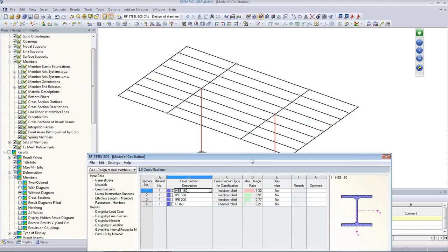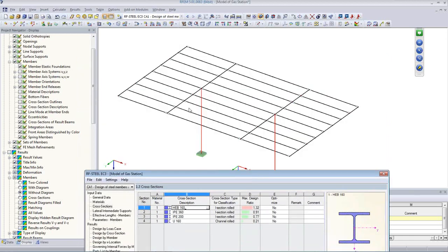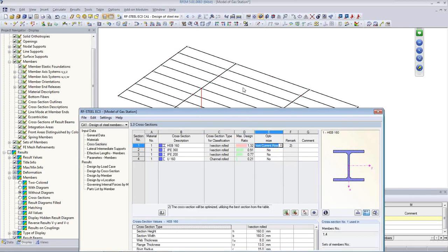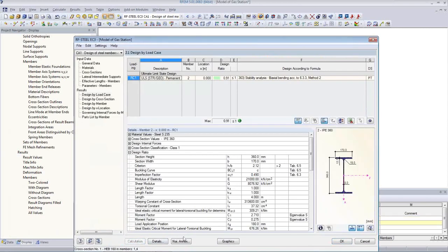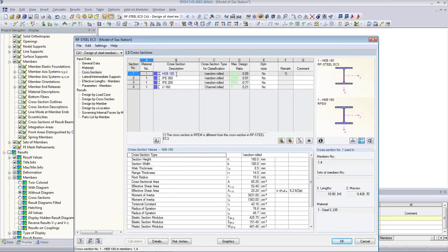I have not taken care of the serviceability and the deflections. So therefore, and I know in these cases we have a problem with deflections, because the columns, if they are weak, the whole roof will kind of wiggle back and forth. So I have to optimize one more time this cross section, and most likely I have to even choose a higher one. Also controlling is the serviceability, and for this probably I have to use even a bigger cross section.